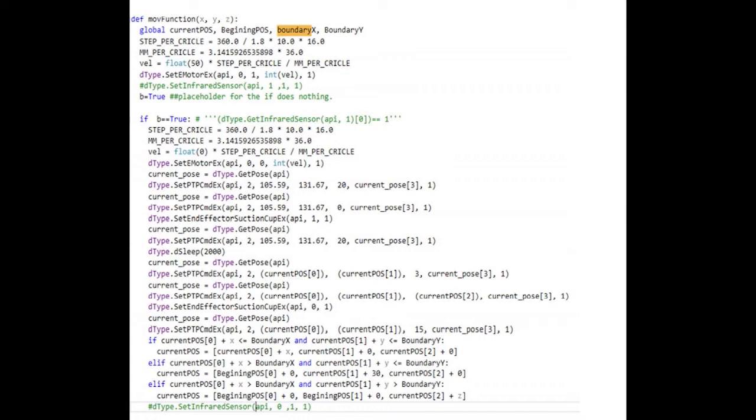The function first activates the conveyor belt, then the infrared sensor. Then there is a check with an if clause where the function checks if the infrared has sensed anything. Then the conveyor stops. After that, the arm will reach out and pick up the box and put it down onto the pallet. After that, there are multiple if-else clauses used for calculating the next coordinates.